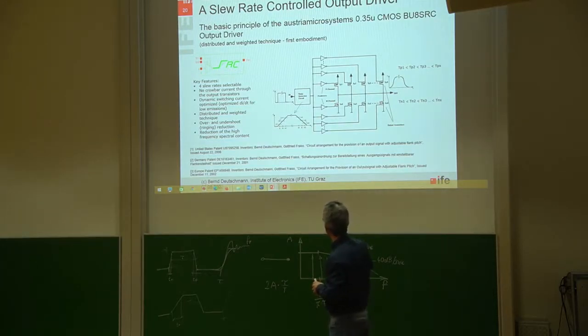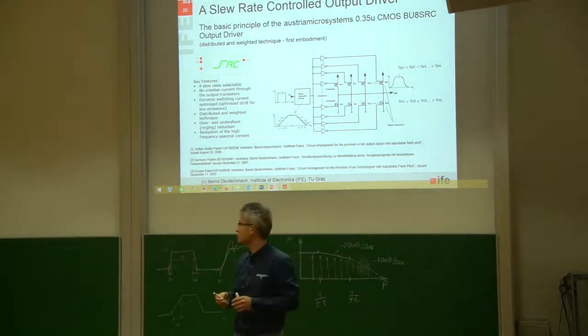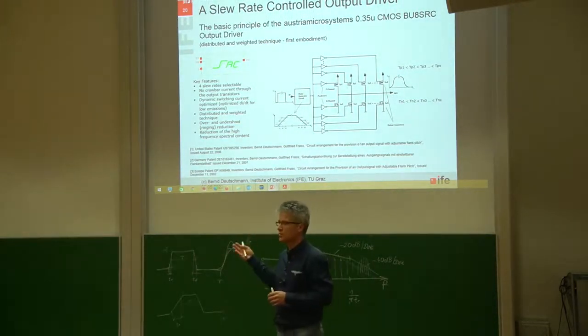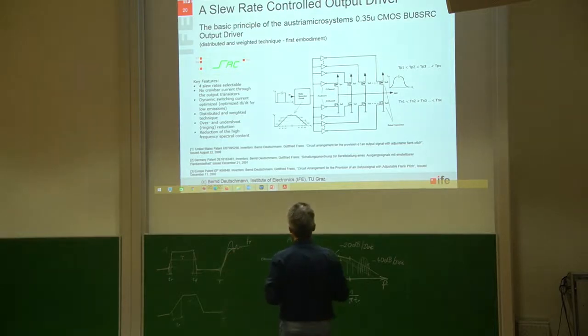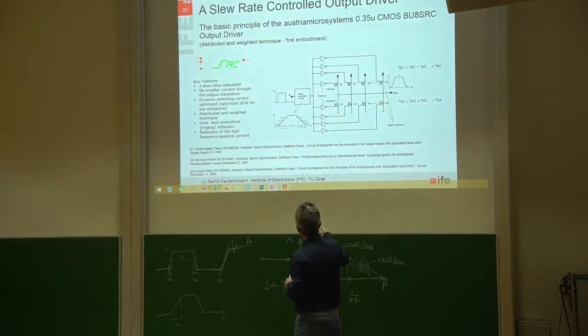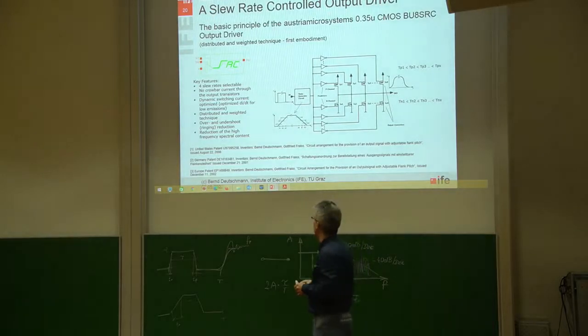And every transistor here got a very small pre-driver. So these are small inverters. They are not producing that much electromagnetic emission. They are just there to drive the gate signal in order to turn the transistor on at a certain amount of time. Here all the pre-drivers are connected together and operated by a kind of ramp generating circuitry.